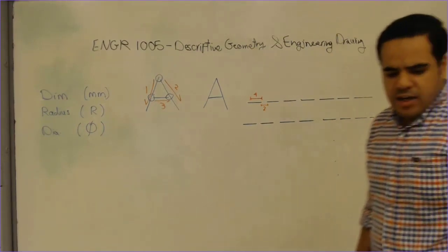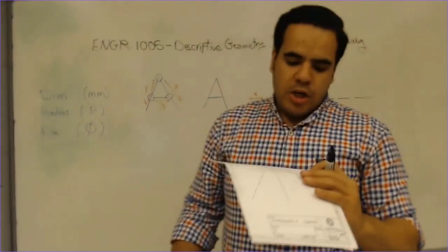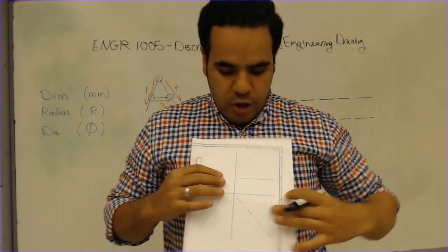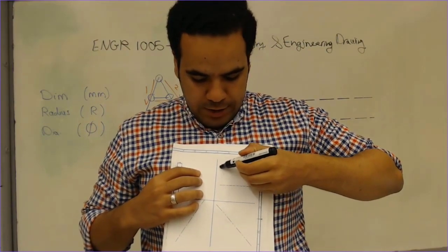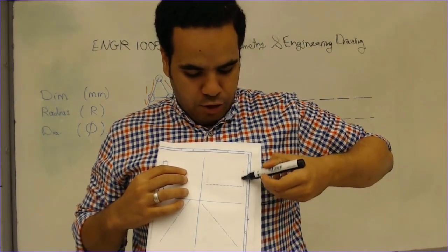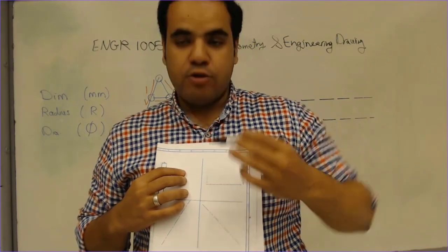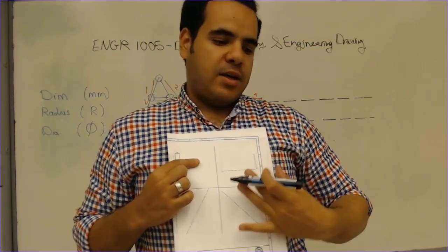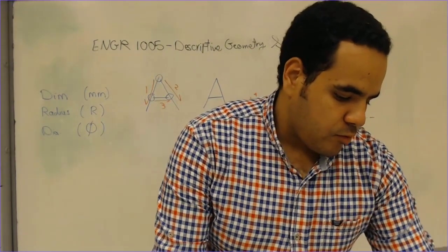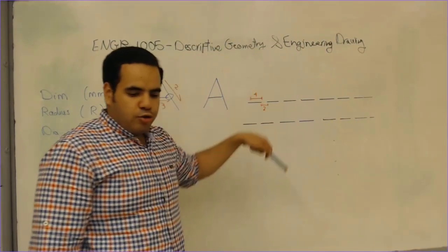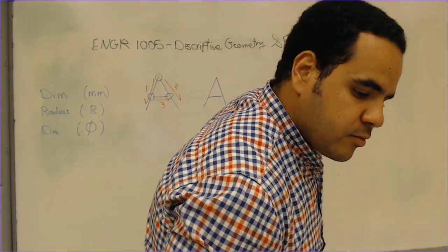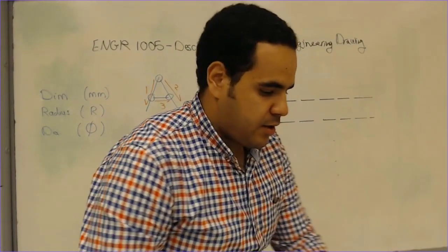Okay, the scale on the A3 sheet here is not like what I said, 4 millimeters and 2 millimeters, but you have to draw 3 copies with the same total length, and then you calculate your 4 and 2 millimeters between these two lines or this distance. Okay, so I'm not going to go on the other two copies. I'm moving now to the third type of lines, which is the phantom line or cutting plane line.